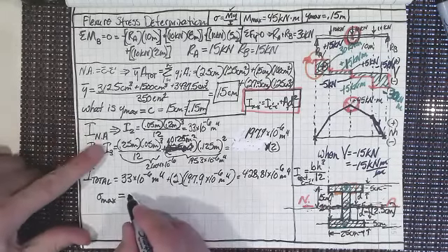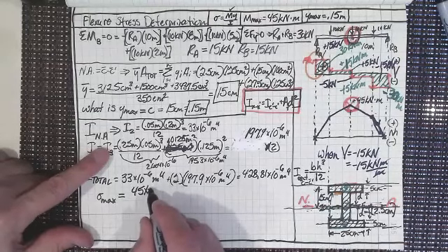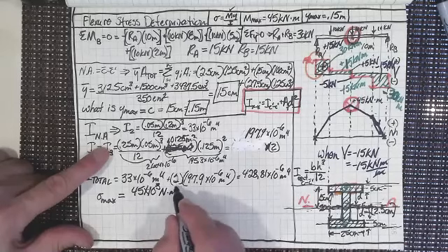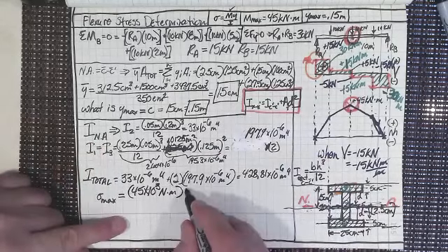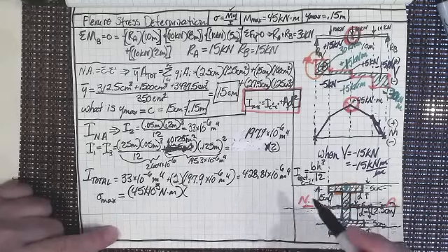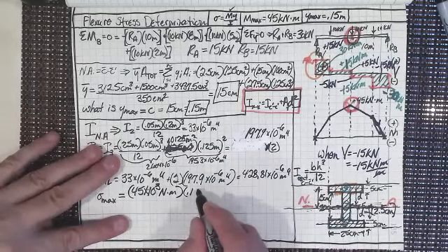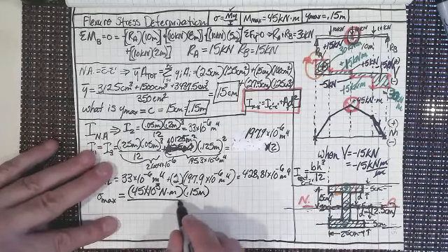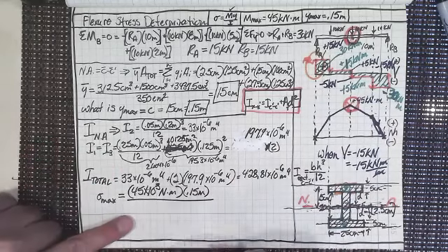but let's do this. So the maximum bending moment is 45 times 10 to the 3 Newton meters, right? Going back to what I always say, even though I don't write it down all the time. I'm always using it in my head. Times y, and y is going to be 0.15 meters, y maximum, and I have that up there too. And now we know what I total is going to be.